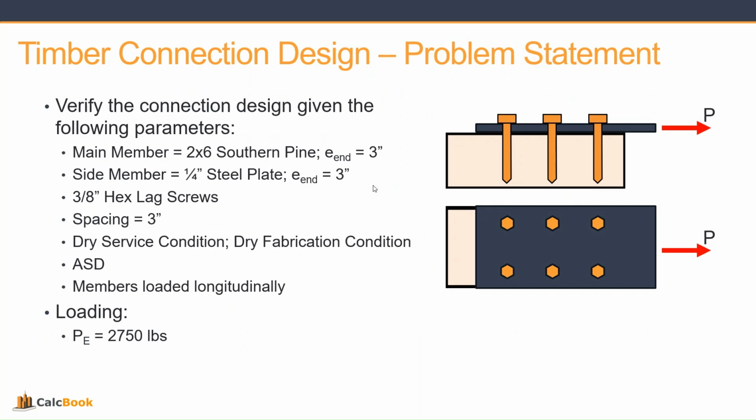We have dry service condition and a dry fabrication condition. We're going to be utilizing ASD, and the members are loaded longitudinally as shown. And our loading is due to earthquake of 2,750 pounds. So let's go ahead and open up CalcBook, and we'll get started on the design.